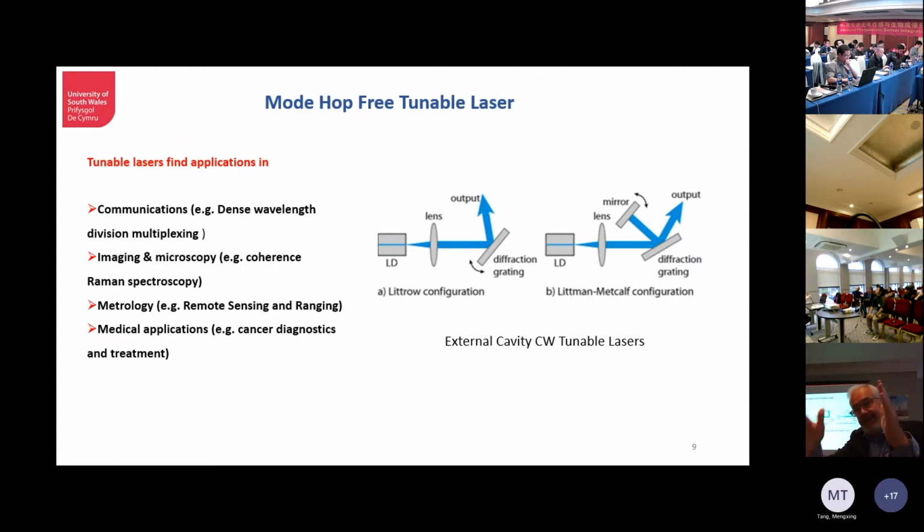And because I've put an AR coating on there, and I've shown a plain facet there, but sometimes it's actually wedged, it's angled, so that any reflections, even with an AR coating, are reflected into the cladding, so you actually eliminate any Fabry-Perot modes that are created within the laser cavity itself. Now, by doing that, you feed light in from an external element, which then gives you a laser which has a much longer cavity length. And if you have a longer cavity length, what that means is you get a much narrower line width, which is what you want for a lot of applications in OCT and also in interferometry as well. And the reason for that is because it's all related around the photon lifetime in the laser.